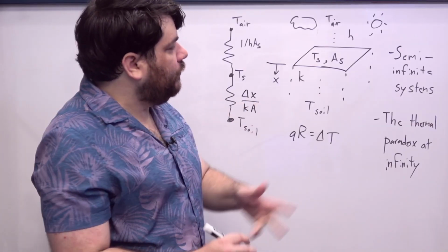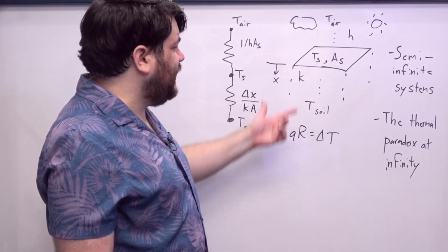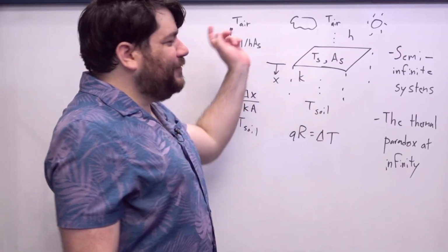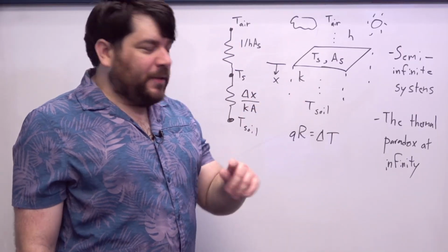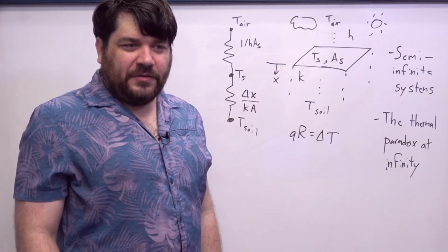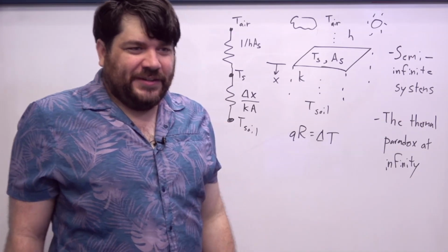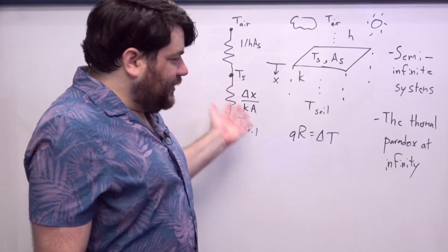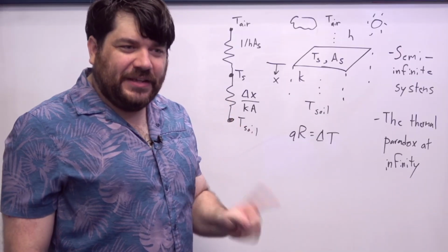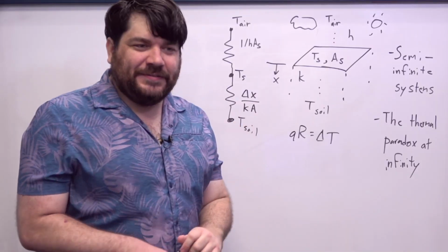And if I had modeled this thing, rather than being some kind of infinite planar surface, maybe some kind of weird contrived infinite cylindrical section, we'd still run into the same problem, right? Assuming that that section was large. For any semi-infinite system, the thermal resistance given by the conductive derivations that we would have to do to get it will always be infinitely large. And so as a result, this is not okay.